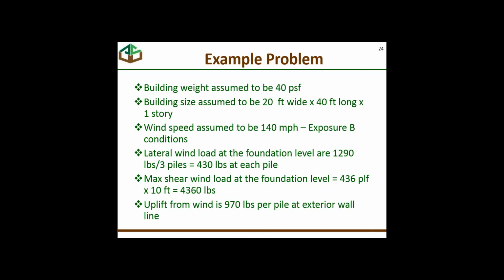So the way this typically works is just like in wind design. You look for the worst conditions and then typically design everything for the worst conditions, unless those conditions are so bad or focused on just one part of the building that it allows you to increase resistances in just one part. We're going to design all the piles basically for the same load.